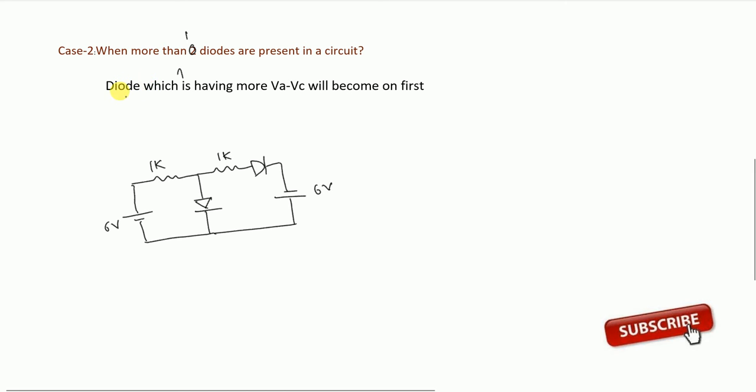See, the solution is, the diode which is having more Vi minus Vc will become on first. If you look at this circuit, he has given this circuit and he is asking us to find the I1 current through this diode. So what is the first step? Open circuit all the diodes. It is 1K. It is 1K. What is the next step? Find out the VAC across each diode.